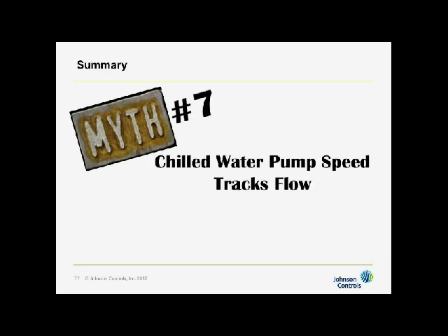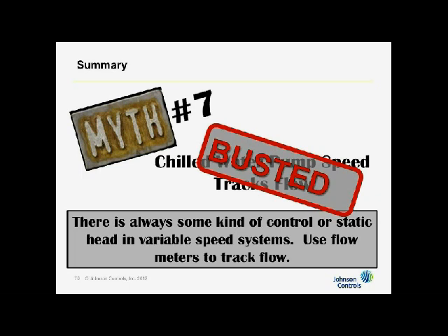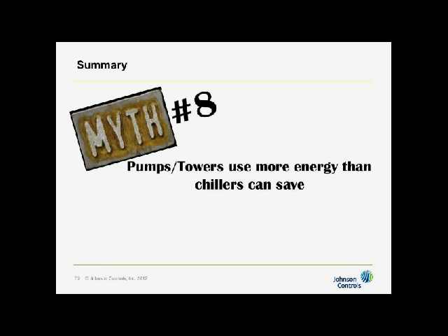Myth number 7, we talked about, said chilled water pump speed tracks flow. That is busted. There was always some kind of control, static head, or other considerations in variable speed systems. You really need to use flow meters to track flow, but more importantly, to get the most efficient plant operation.